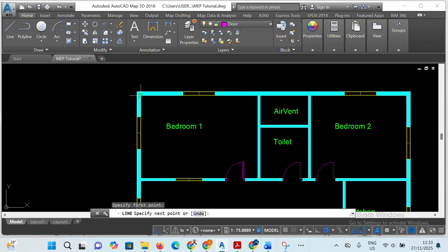From here we start the point, and the first one is 44 inches, press enter, then 88 inches, press enter, then the next one is 88 inches, press enter, and the final one, which ends here, will be 44 inches, press enter. So that ends here at the start point.